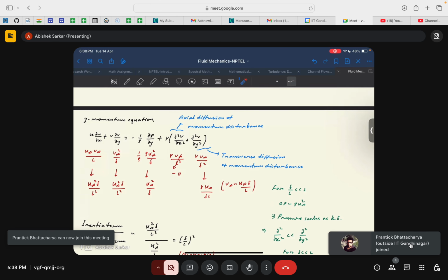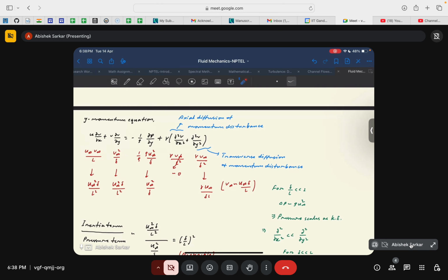Considering that we know that the flow is driven by the inertial effects, we will consider in this case, at least for the boundary layer, that delta p will vary as rho u infinity square, as the kinetic energy term. I should just write it for your reference. It is not universal. Again, this will not be asked in your exam or of this course, but it is something important for you to know if you want to take a career in fluid mechanics or study fluid mechanics further.